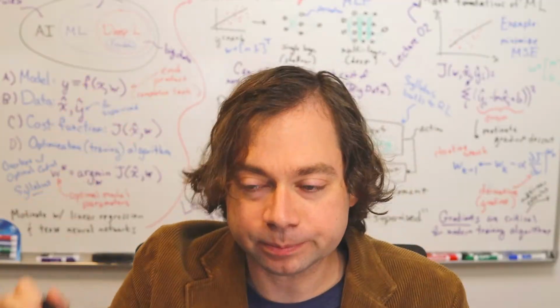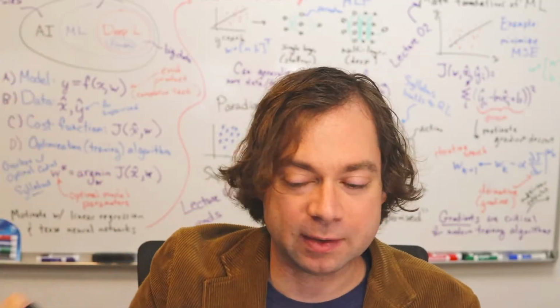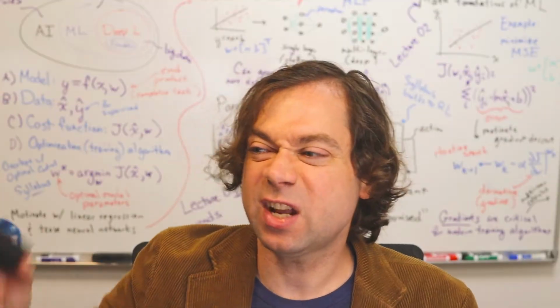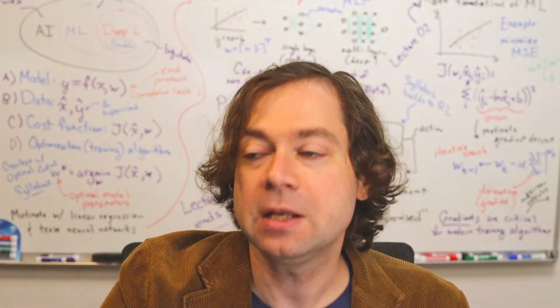We don't have to put a PD controller here and a PD controller there. We have to tune up the gains appropriately to get them right, and that would change with the mass of the arm and everything. Because the operational space controller is aware of the dynamics, we just tell it how we want it to accelerate, right? Okay, that's the big picture. That's what we want to accomplish today.